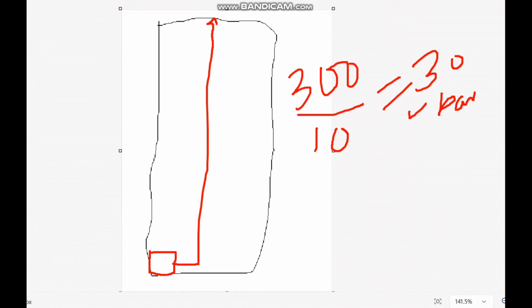Static head is 30 bar. That means all your pipes should have 30 bar minimum pressure rating. The pump pressure head will be very high. So all this will increase the limitation in the system. So this is one of the important things.